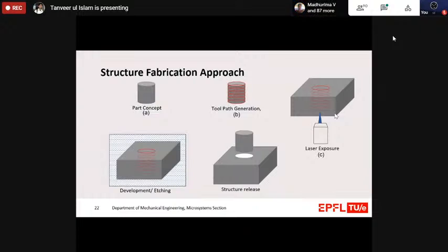Now, as you can imagine, like other 3D printing processes, microstereolithography and others, we also have to use the layered scanning. Like I said, the minimum spot size, the minimum area that could be affected using this process, is 3 microns in diameter, equivalent to the wavelength of the laser we use, and the length of the spot is around 10-20 microns depending on the laser, as well as the optics used.